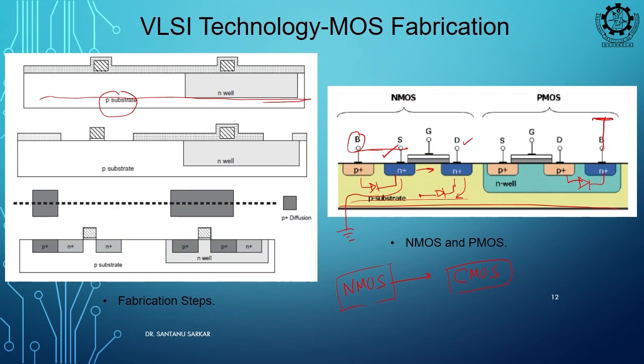These are not real structures, but equivalent structures. For example, if I have a connector, ideally it should have 0 resistance, but maybe a small resistance of milliohms is there. This resistance we call a parasitic resistance, which is unwanted.